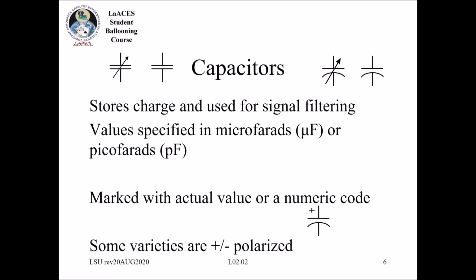Unfortunately, all the different vendors of capacitors have not made a great standard like they did for resistors, which I'm very sad about. And so it's always a hassle to pick up a capacitor and figure out what the value is. And multimeters are oftentimes not accurate enough to really give you a proper value. So if you get some capacitors, I would recommend always saving the bag that has the part number so you can go back and look at what it actually is.